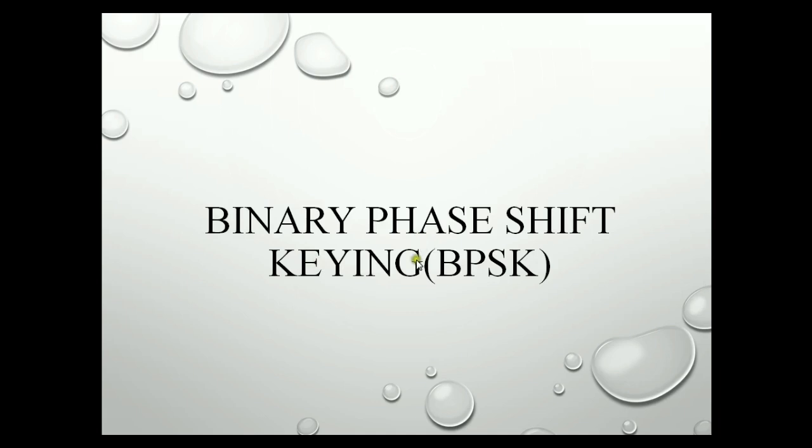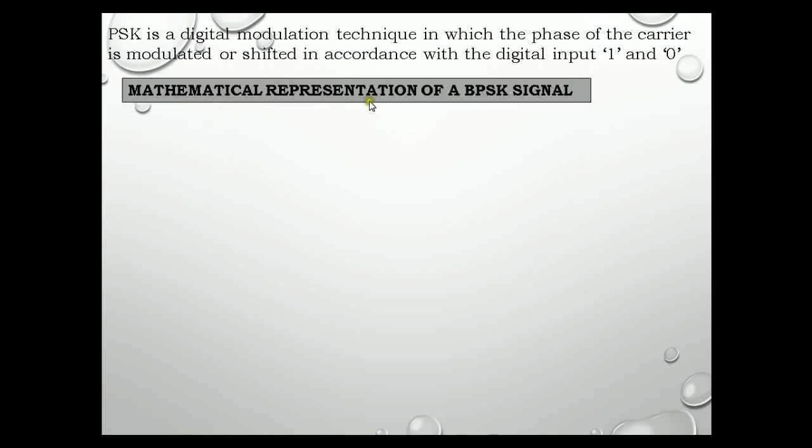Binary phase shift keying, or BPSK. BPSK is a digital modulation technique in which the phase of the carrier is modulated or shifted in accordance with the digital input 1 and 0. Next we will see the mathematical representation of a BPSK signal.